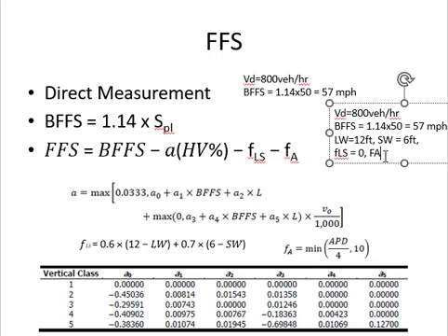What is my free flow speed then? I just need to put the percentage of heavy vehicles here. This is 0, but you don't need this one as well, right? No, A is 0.033. You still need this one. So 0.033 times the percentage of heavy vehicles. So my free flow speed is how much? 56.9.